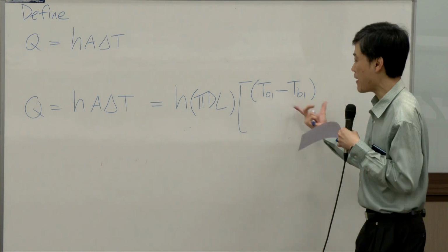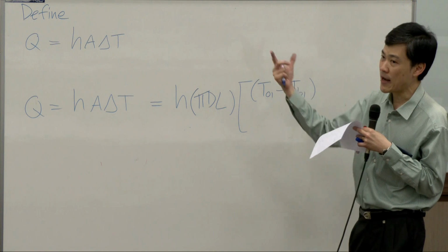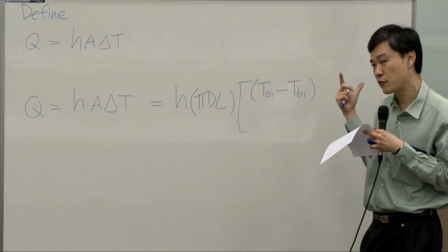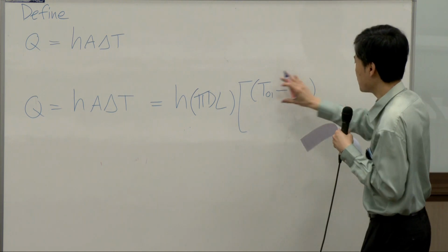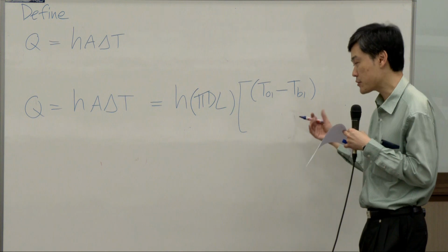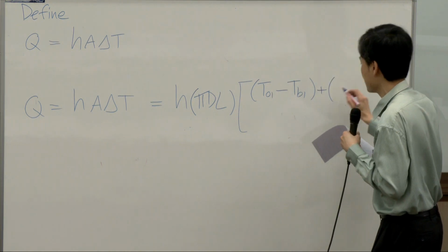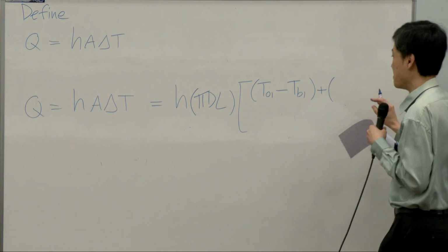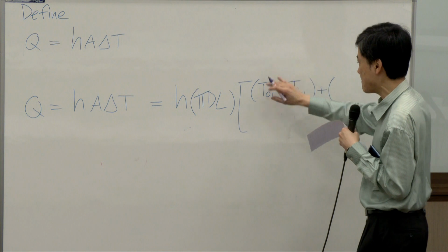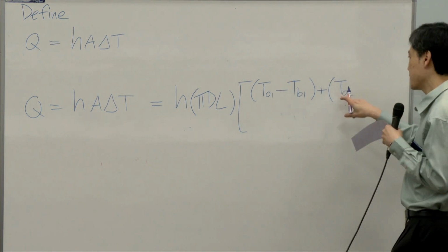But using the driving force at the inlet alone seems weird because the whole pipe, heat transfer is done continuously throughout the pipe. So we need to somehow find the average value of the driving force. In order to find it easily, you just do the arithmetic mean. So this is the driving force at the beginning of the pipe. I'm doing the same at the end of the pipe.